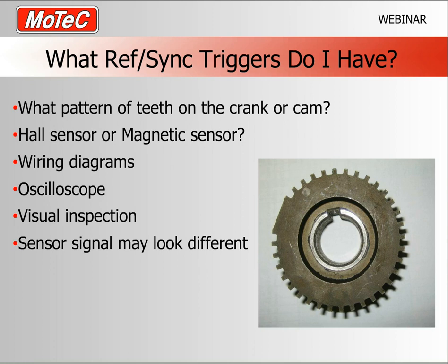What ref sync triggers do I have? This is quite a broad subject and there is a reasonable amount of experience involved, but let's say you were ringing someone at Motec, perhaps myself or Dwayne, to ask what setup you need in the ECU. The kind of things we'll be needing to know are what is the pattern of teeth on the crank or cam, or specifically for today, you need the crank and cam.